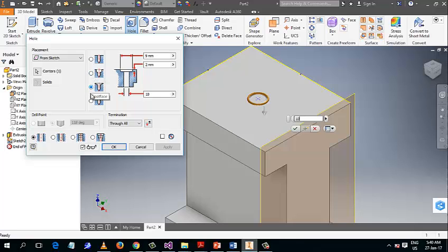If you understand engineering terms, this is machine design, don't forget this course is about machine design. There are some bolts that look like this. They will rest inside, they will be flanged. So you can create a flange hole to allow for the head of the bolt to rest here. Call it counterbore. Then this one is countersunk because it is like a Y shape. Then we have spot face. So it depends on what you are doing.